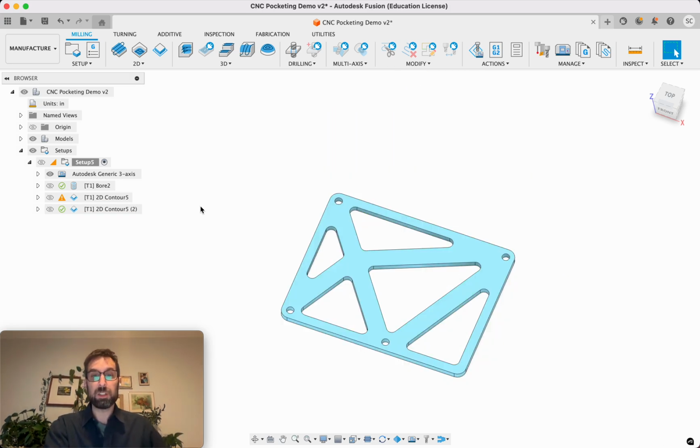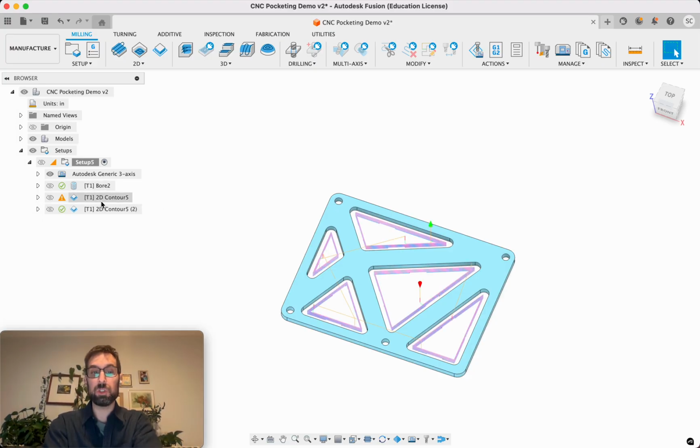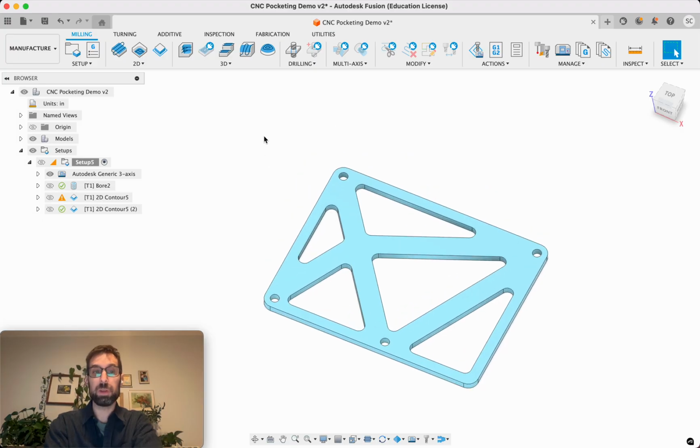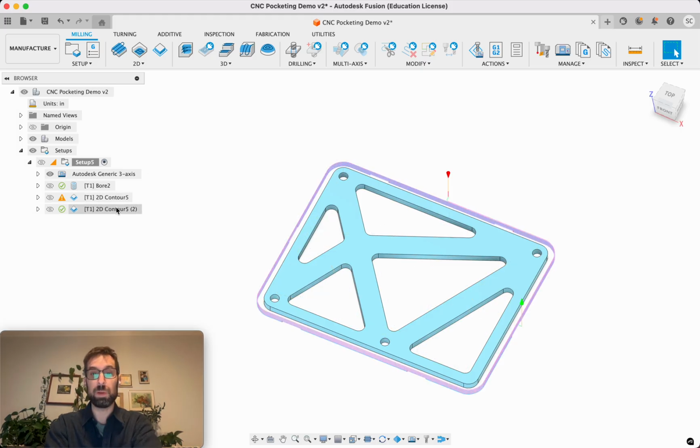The final thing I need to do is called post-processing, and that is to convert these toolpaths here from Fusion 360's language into ShopBot language, that's called G code. So I am actually going to show you how to create a post-process document for each of these toolpaths.